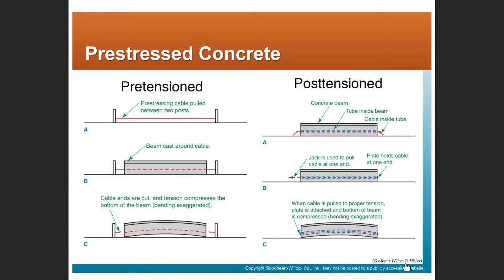Now, the only problem with pre-stressed concrete, there's probably a number of problems, but you really want to be careful if you're the electrician or the plumber that's got to drill a hole in that concrete slab to run their conduit or to run their drain lines. You better know where that post-tension, where that steel element is located, or else you'll have yourself a nasty surprise.